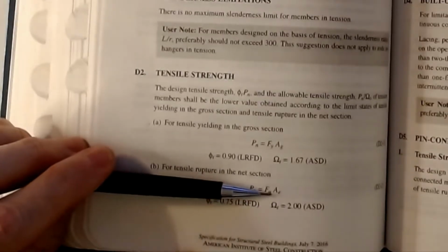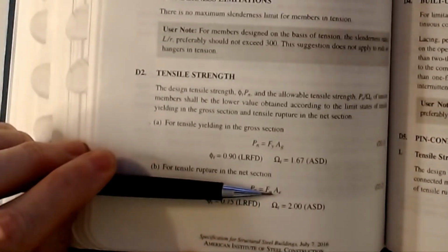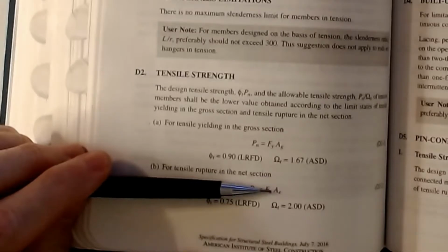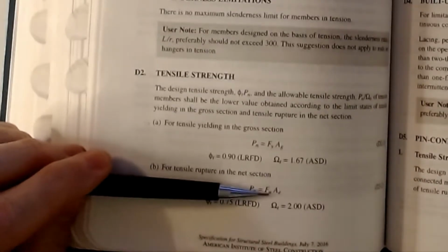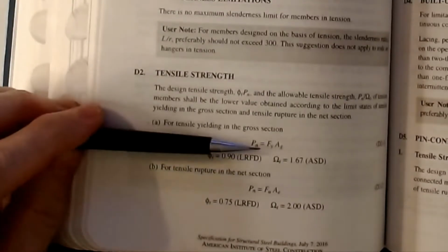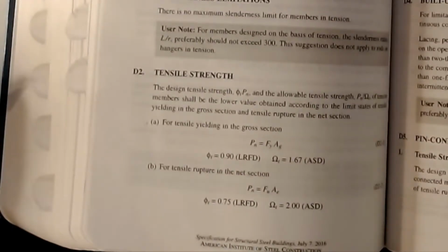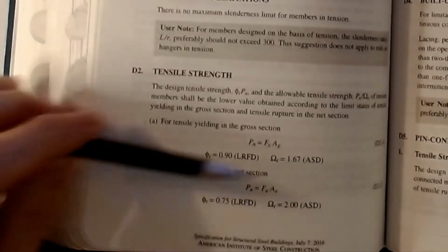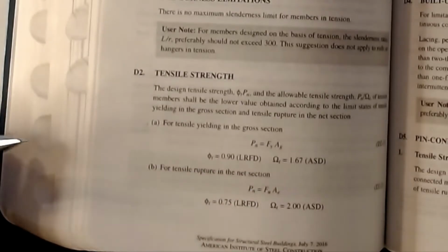So you have to do a different calculation on the area, and this leads us into a topic known as the effective net area, and it leads into shear lag and some requirements on that. But this is the basic equation. So the trick is, how do you calculate Ae? We'll cover that in the next video. So the gross yielding phenomenon uses the gross area. This is the A that's tabulated in the front, in the early section properties of the book. They always tabulate Ag. The trick is how I get from Ag to an Ae.